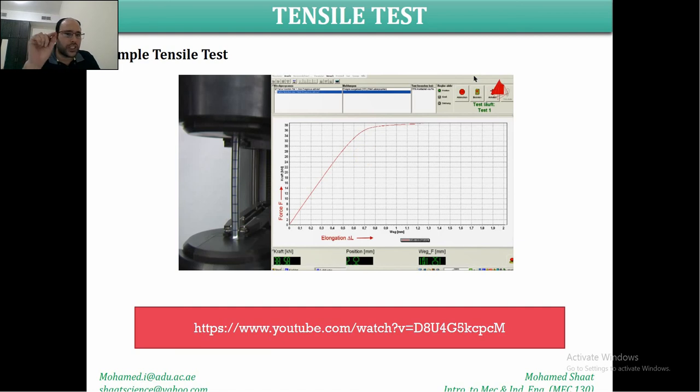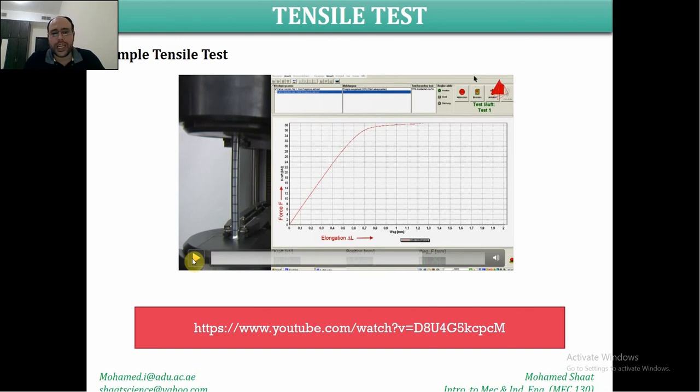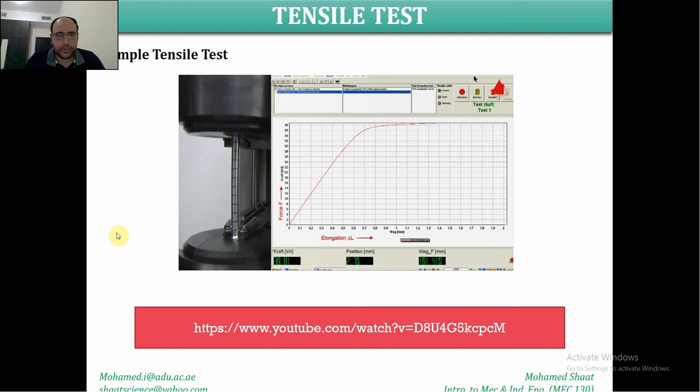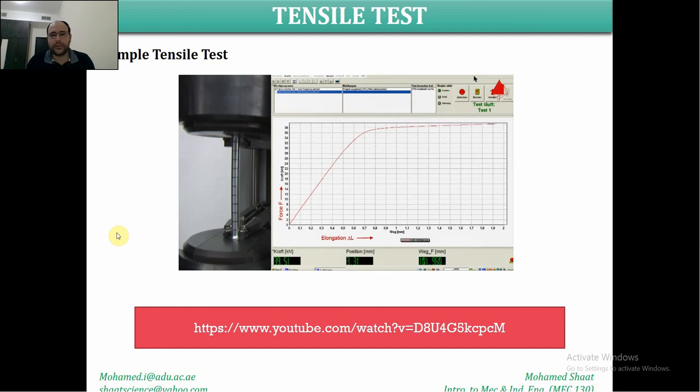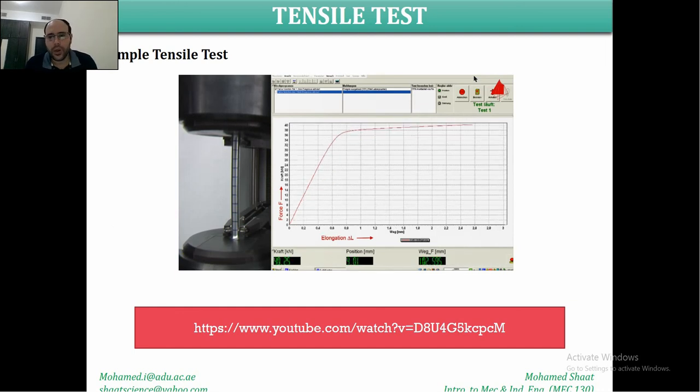So that's why this material type is known as a material without yield point phenomena. But steel is a material with yield point phenomena. Why? Because we can clearly see the yield point or yield region within the stress-strain curve or the force elongation curve. Make sense? There is no distinct change; there is a smooth and gradual transition from linear elastic behavior to plastic deformation.